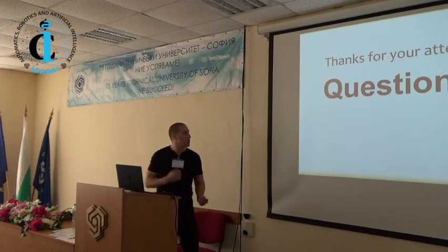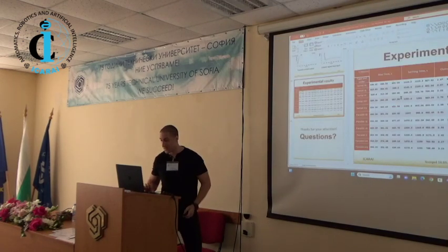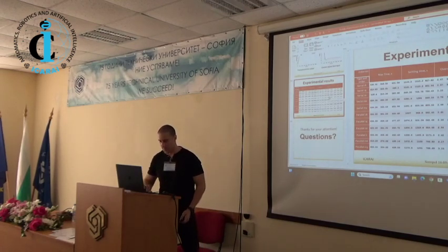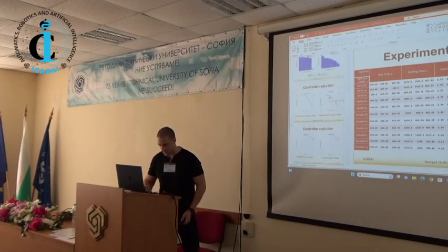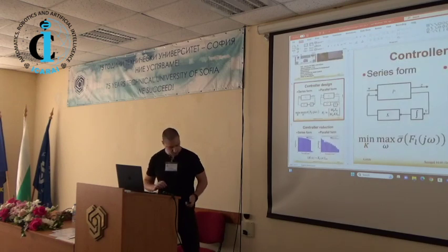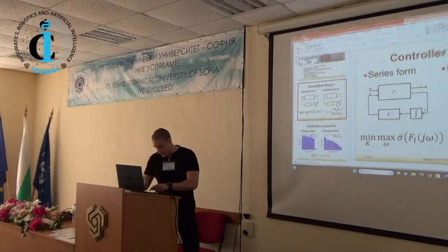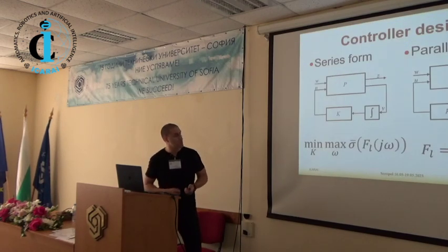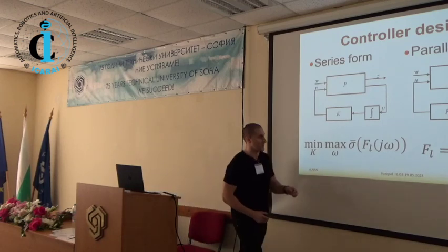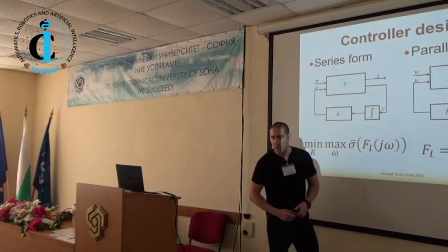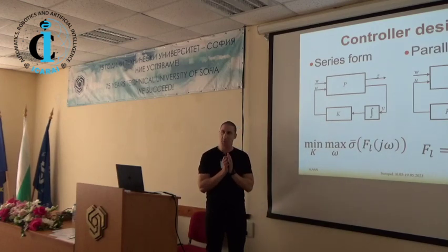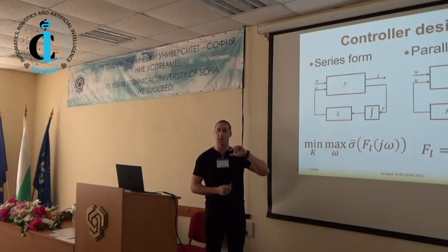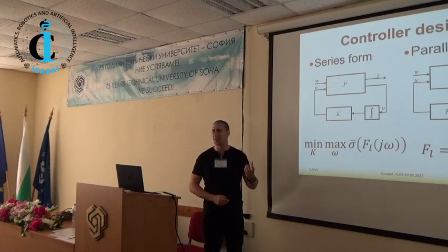We chose it in a way to... It's very important for the quality of the result. I decided to skip this in the presentation, I'll tell you, just let me find my slide. Yes, the shaping filters. First, for the output sensitivity function, we chose a desired bandwidth, plus a maximum for the sensitivity function, and a desired error in the state.